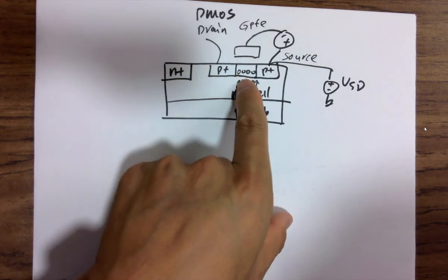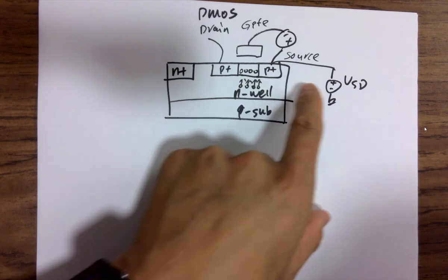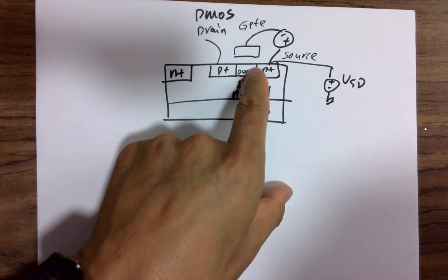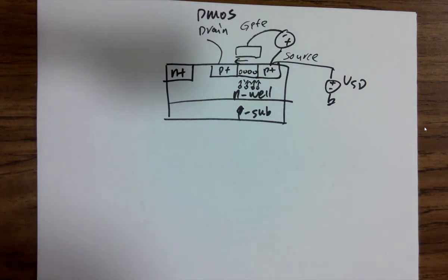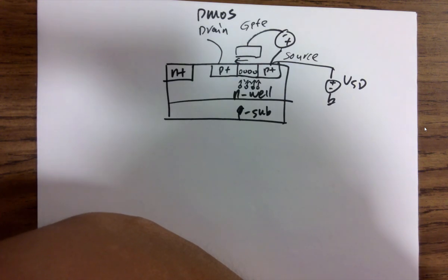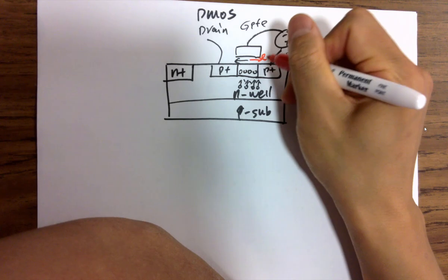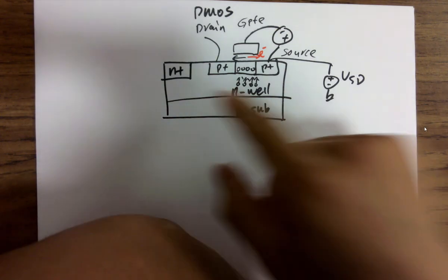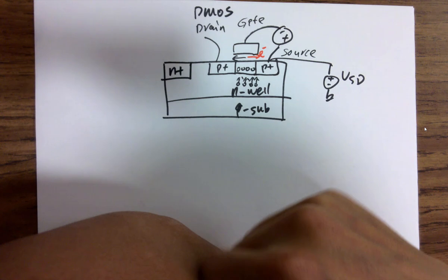After you turn on the channel by a negative voltage and you're forming a layer of holes, you apply a positive voltage here, and it's going to expel holes from this source terminal. So the holes are moving in that direction by concept. It's basically electrons going this direction. So it seems like that's a drain of holes, that's a source of holes.